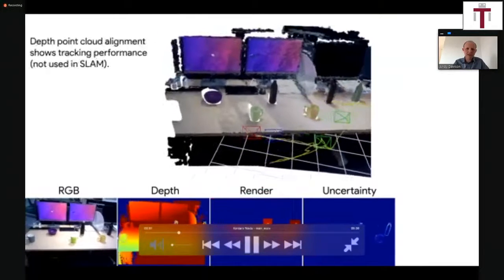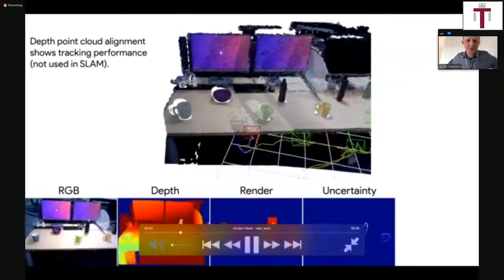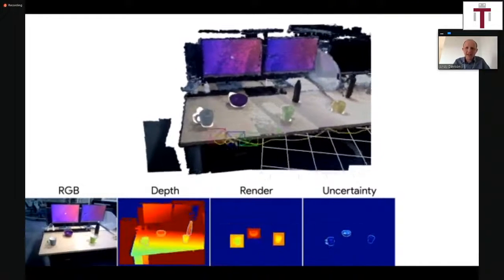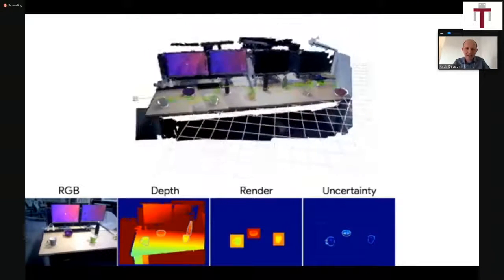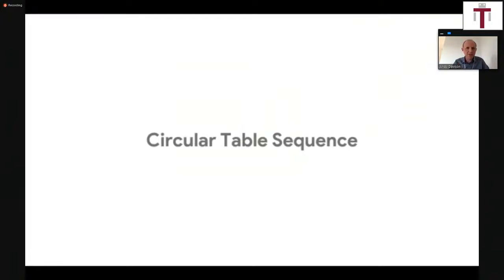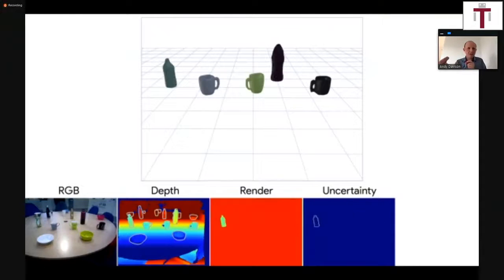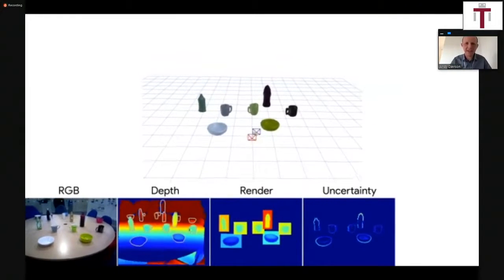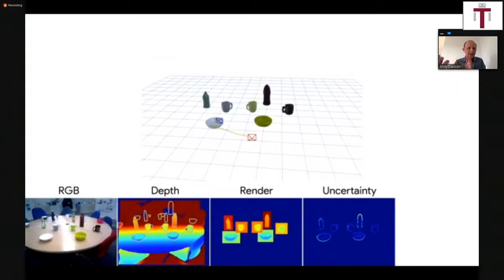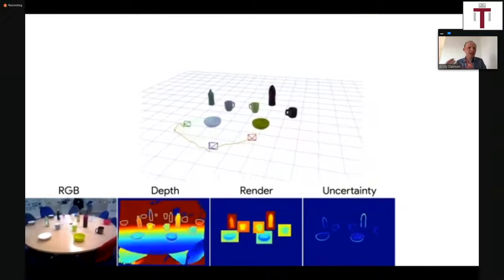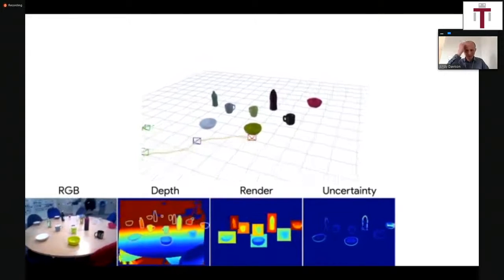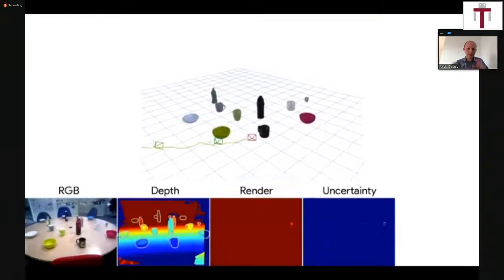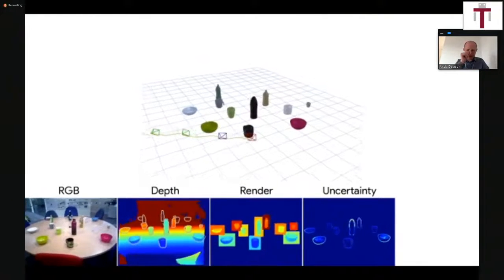What we focused on here is whether we can now use these sorts of models for quite useful things in a SLAM context. Here you'll see that for each of these objects in the scene, the first time that we observed it, we basically optimize over the coded parameters of the shape model of that particular class of object until the reprojected shape of that object matched well with the depth information that we've got. So just from one depth view, we can get quite a reasonable estimate of the shape of the object. From multiple views, we can improve that even more.